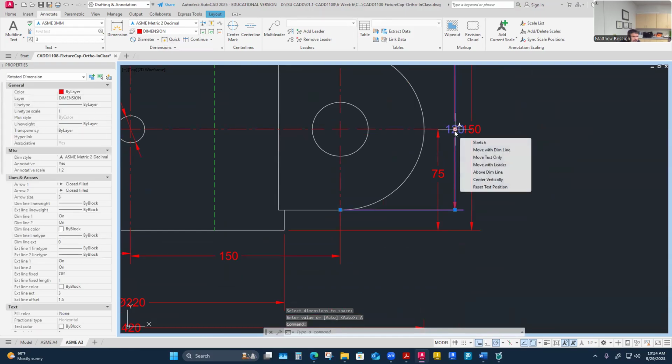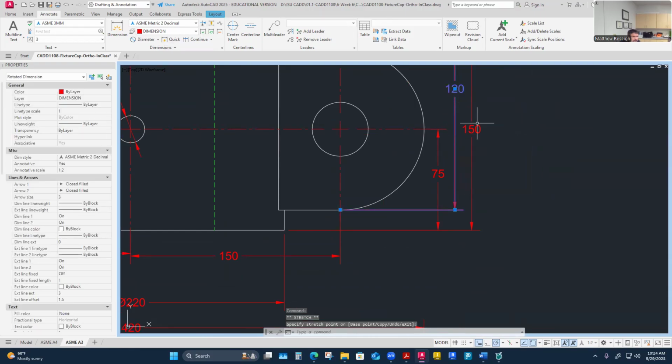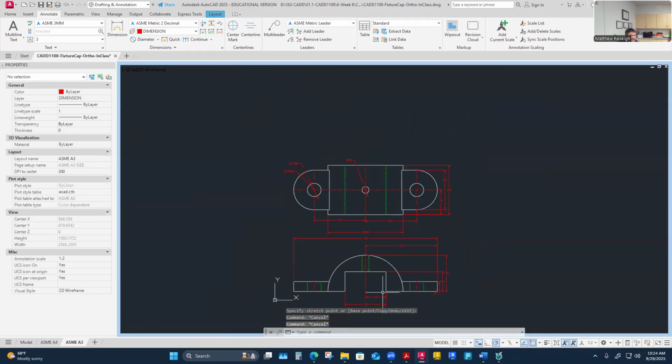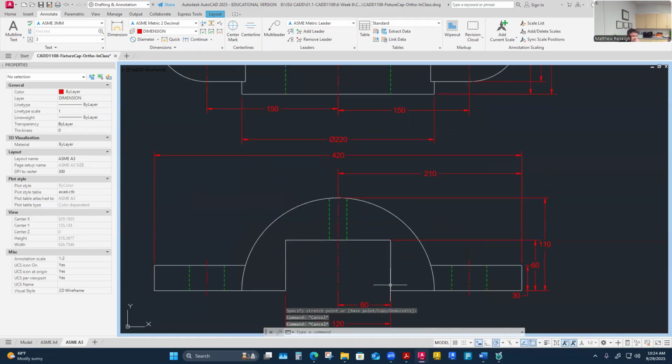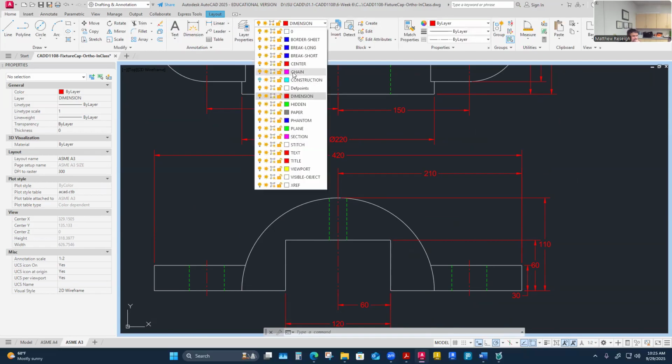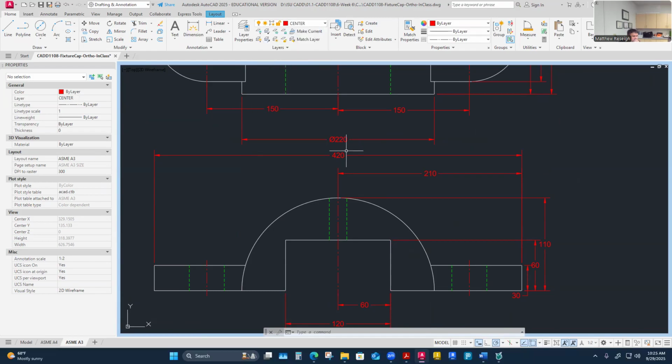Yeah, what do you think there, Riley? The large circle on the bottom, why don't you have the center mark for that? The large circle here. Oh, like here? That's not a bad idea, actually. Yeah, that's a valid point. If I went to my center mark here, I don't think it would be wrong to add that actually. And if I did that, I would probably pull back the mark to right here, like we've done on one of those other parts.